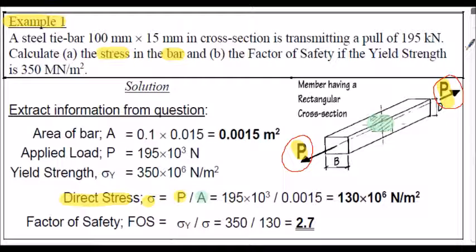In dynamic situations, that's not the case. The force system is unbalanced, and that's what's causing the acceleration from Newton's second law. But it would be very nice if we could actually analyse dynamic situations using statics. And that's the reason engineers often like to use D'Alembert's principle, because it changes a dynamic situation, an unbalanced situation, and it makes it into a static situation, a balanced system.